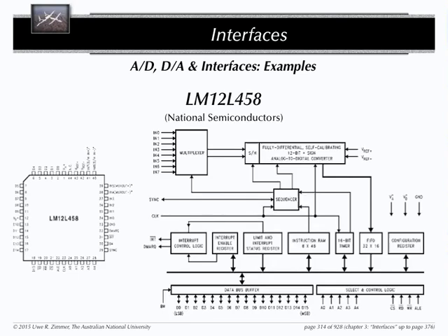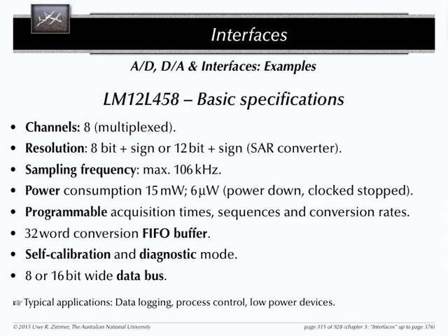Okay. So, what do you find inside that thing? 8 multiplexed AD converter channels. Okay. What does that mean? What could a multiplexed AD converter possibly mean? Read from one of 8 analog signals at a time. Yeah, read from one out of 8 signals which are wired to that controller from the outside.